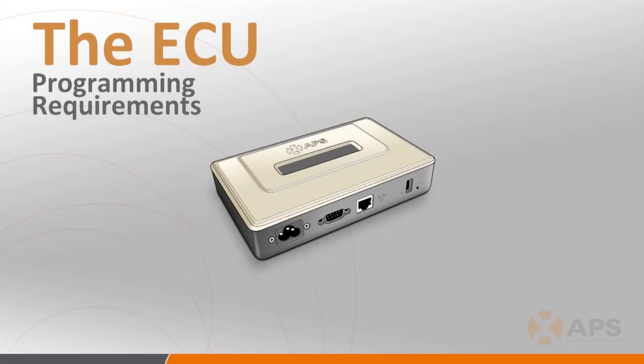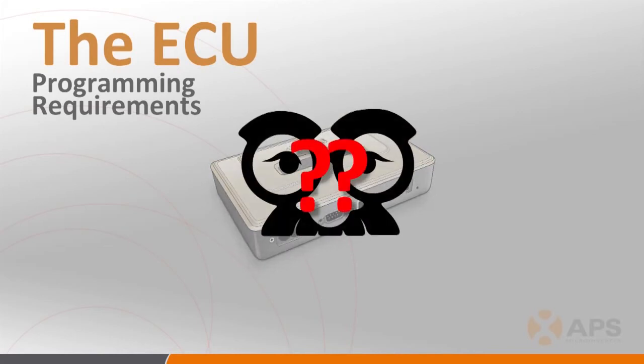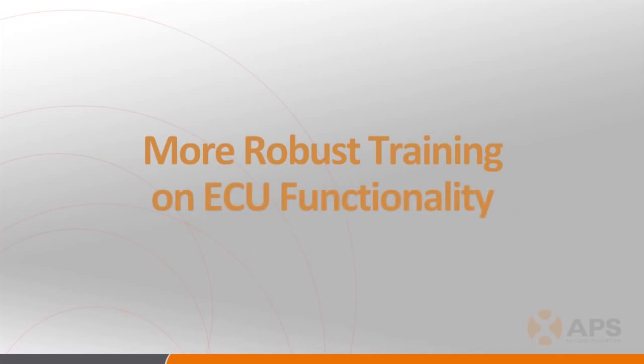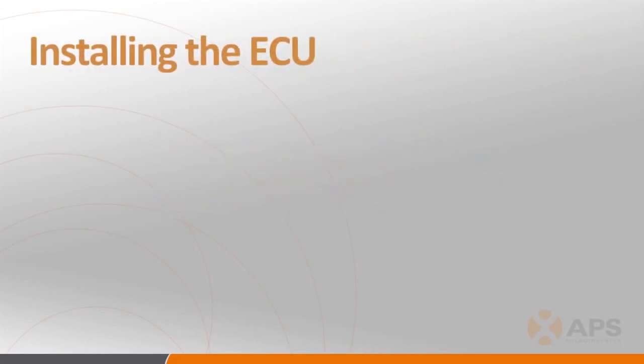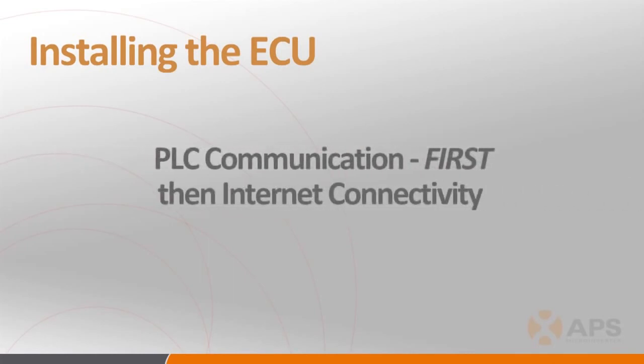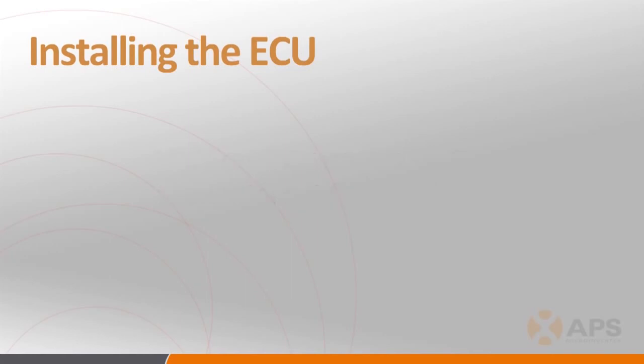Failing to perform this part of the overall installation process will result in the ECU not being able to recognize the system's inverters. We will be going over the detailed ECU programming instructions in another training presentation that is focused entirely on the ECU functionality. When installing the ECU, it's always best to establish PLC communication first, and then internet connectivity.